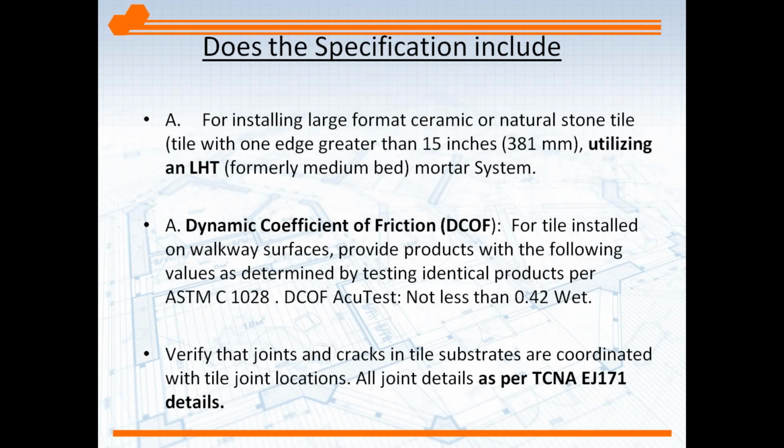Okay, so for installations of large format tile, what does the specification include and what does it need to include? So utilizing an LHT, as I mentioned. Now, if you're looking at your specification as an installer, if it doesn't call for an LHT mortar and you know the tile is larger than 15 inches, you know that you're going to be beholden to use that LHT. It's the proper product to use. If you're a specifier or architect, I would suggest language that includes the utilization of an LHT mortar for any tile over 15 inches.